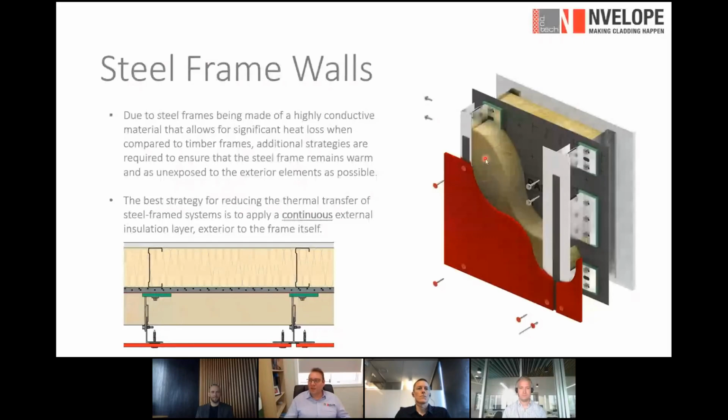We've seen situations where they're using it almost like a packer and bolting substrates through the insulation. Ideally, we would like to see the load being transferred directly through to the slab through some form of structure.